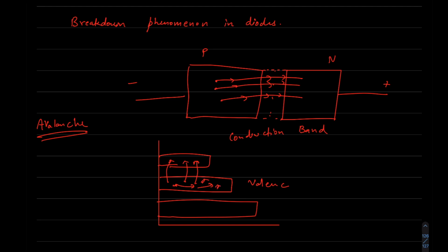Due to the electric field, they accelerate so much, they get so much kinetic energy, that all the electrons start going to the conduction band, and a big flow of current happens, and our diode is carbonized, and then it's dead basically. So that's so exciting, destroying something. Yeah, let's imagine I did not say that. But yes, there's an exponential increase in current and our material is destroyed.